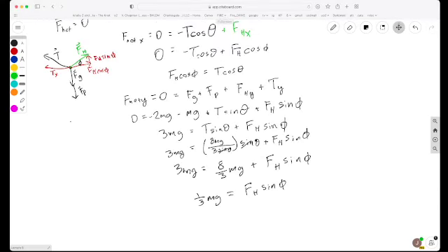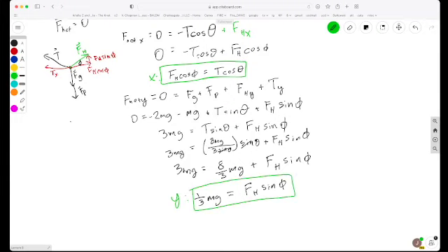So now we've solved for the x component of our hinge force up here and the y component of our hinge force down here. The expressions I have written out are very explicit: the x is Fh cos phi, the way we defined it, and the y component is Fh sine phi.